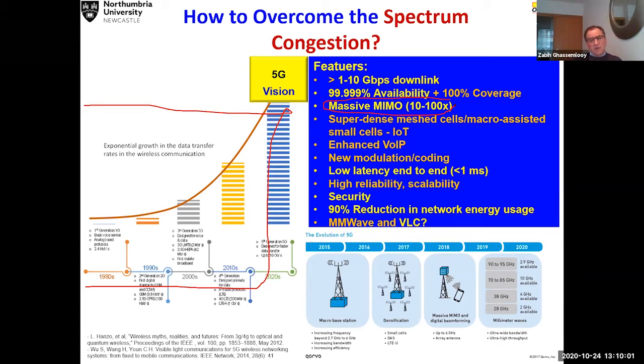To implement massive MIMO in the RF domain, well, the technology is based around millimeter wave and possibly terahertz. So these are very high frequency, short wavelengths. And then you can ask the question, how massive can a MIMO be if you are going to use millimeter wave? Or is there a limit for massive MIMO within the RF domain? And you will find that actually there is. Maybe you're talking about 100 antennas.